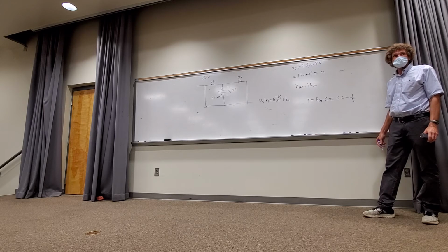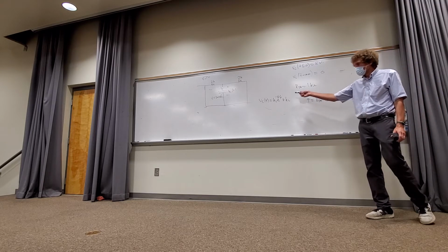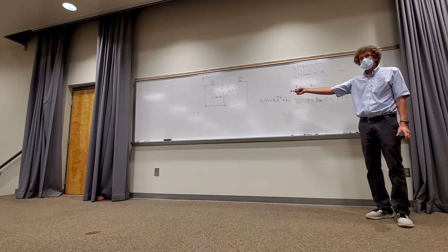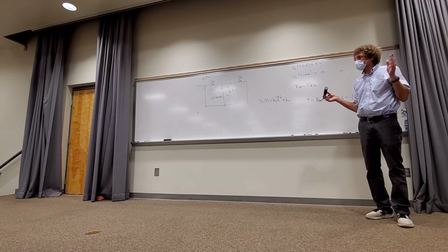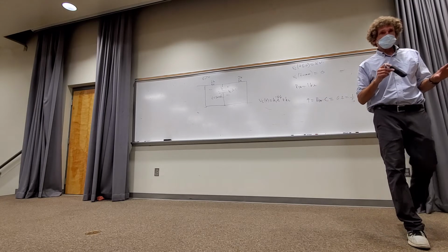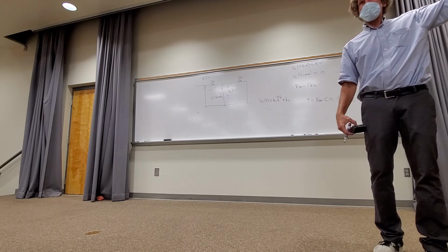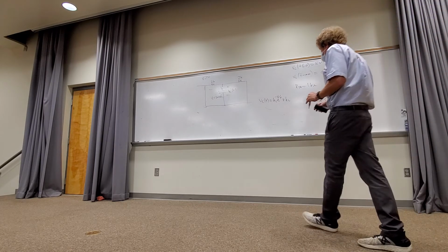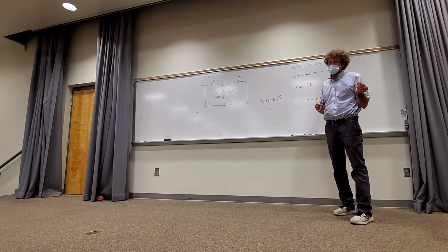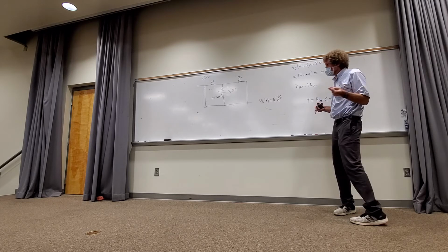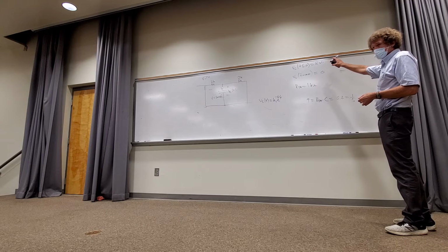Can you all see it in the back, guys? All right. So now, if we have that, we go back to here and we evaluate K1 and K2. Well, K2 is the given. Do you remember what K2 was? Anyone? The 0? Yeah, but what? You're right. K2 is really the voltage on the capacitor as t goes to infinity, right? How many see it's 0? Right? Y'all with me? So if it's 0, then don't even write it down. And if it's 0, y'all know that K1 is just the voltage at t equals 0, isn't it? Right? It has to be. So K1 right there is just 8 volts, isn't it, class?